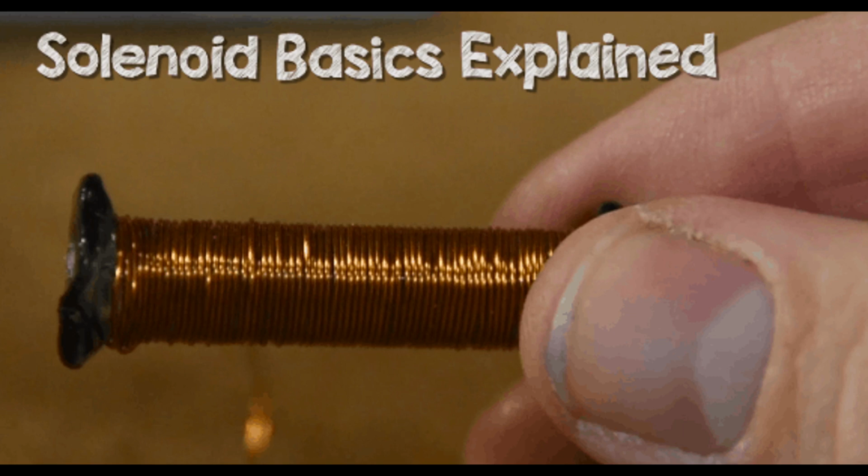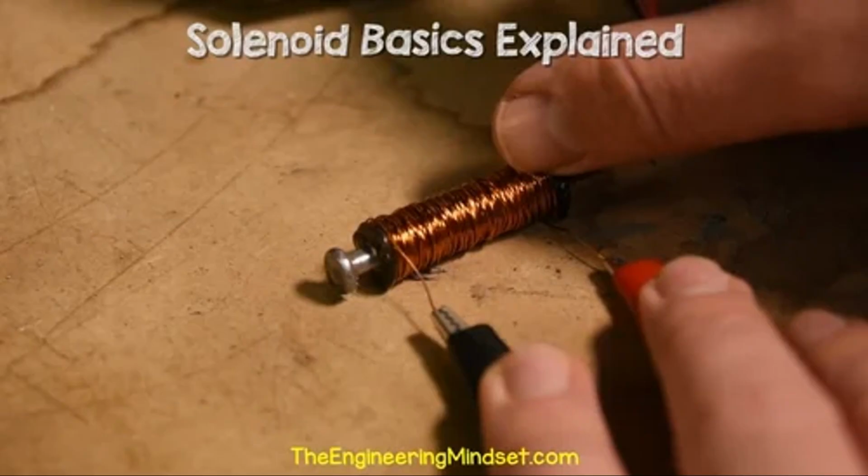Control mechanisms. Solenoids can be controlled using various methods. Simple solenoids may operate with a basic on-off switch, where the coil is connected to a power source to activate the motion. More complex solenoid systems can involve feedback sensors, control circuits, and microcontrollers to precisely control the duration and intensity of the current, allowing for fine-tuned motion control.